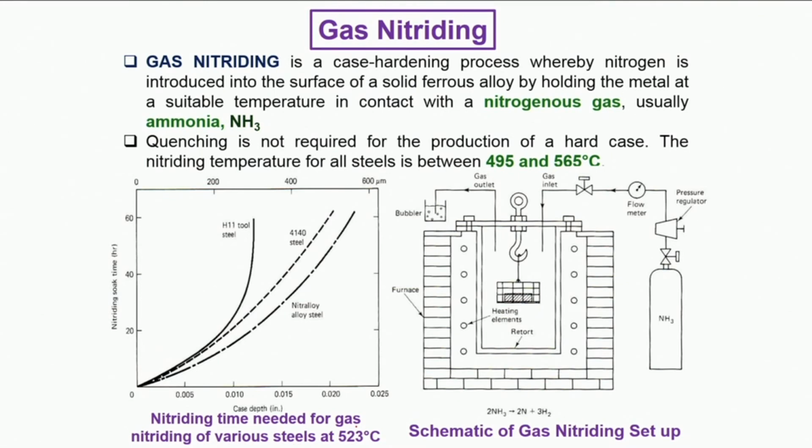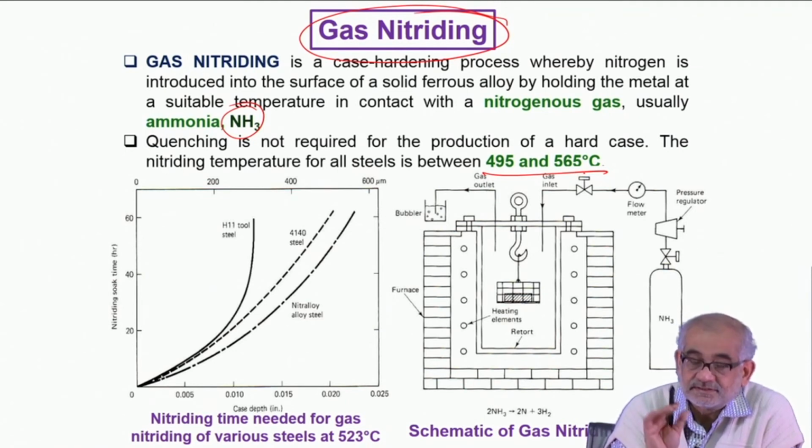So when we want to carry out an actual experiment of nitriding, gas nitriding is one of the most popular and effective methods. Here we use ammonia as the precursor for introducing nitrogen. As I mentioned right in the beginning, in the nitriding furnace, the ammonia dissociates in this typical temperature range, around 480, 490 to about 550, 560 degrees centigrade. That is the optimal range where the diffusion coefficient is fairly high, and you don't need to heat more than this, because within a short distance nitrogen buildup is fairly high to start forming the higher nitrides.